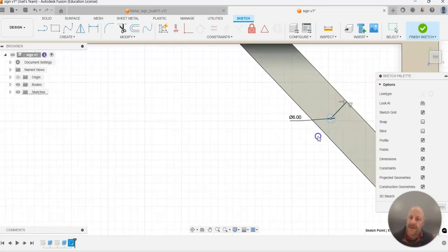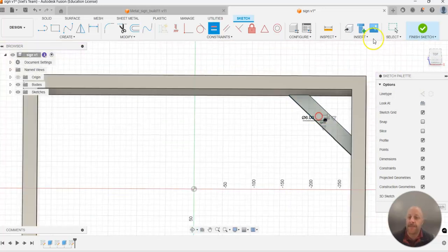And you can see that now moves in the center. One more thing to do, I'm going to draw a line from the center. So L is a shortcut, and there's a line from that circle center to there. So I've got 2 lines there now. One quick little trick, if I press on the line and press X, it converts that line to a construction line. And you can see this now moves up and down in the center. One last little trick here, if I use the equal tool, I'm going to say that that line and that line are equal, and that centers my hole.